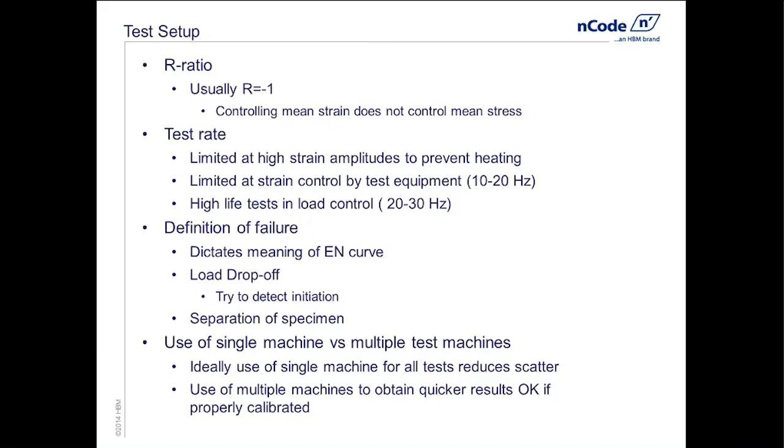Now, as we look at very high cycle strain life tests, there's minimal plasticity, and we can get away with assuming that load and displacement are the same thing. So you'll see a lot of times test labs will go in and, at the higher life regime, switch over to load control and allow you to run at a higher speed. So we can at least up the speed of the test for those high cycle regimes and minimize any issues because, again, there's minimal plasticity there. So we can get higher speeds.